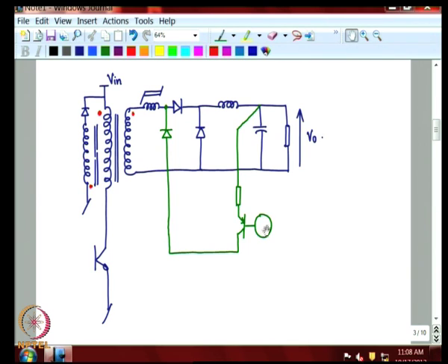Now, how do we give this gate drive? This gate drive should be such that the bias current, the base current biases this transistor at an appropriate operating point such that just that correct amount of current is flowing through the inductor in the negative direction to reset this core to an appropriate flux level for starting in the next cycle when this switch is on.